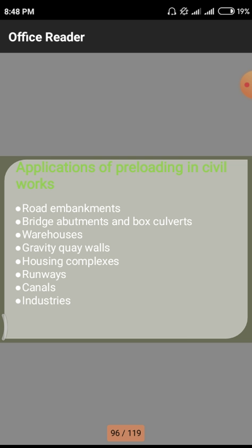But in the case of aeroplanes and other army purpose aeroplanes, we have to implement a huge amount of tracks with different principles, alignments and elevations, so we have to use these runways with preloading techniques. Why? Because of the sudden drop of the aeroplane load onto the structure, there is a definite chance of settlement of the land and the runways themselves, so we have to encounter these sudden settlements by implementing preloading techniques and other water works on the fields.